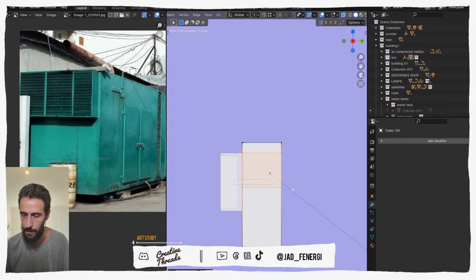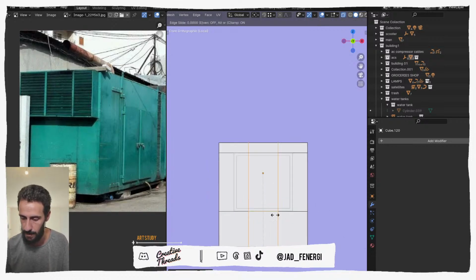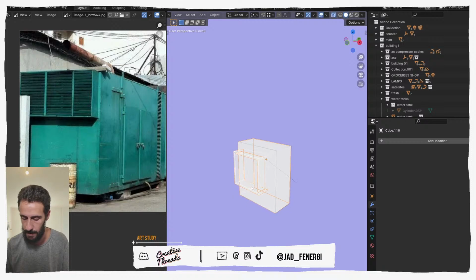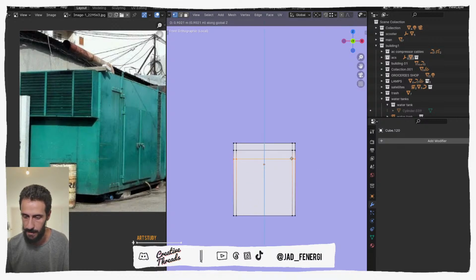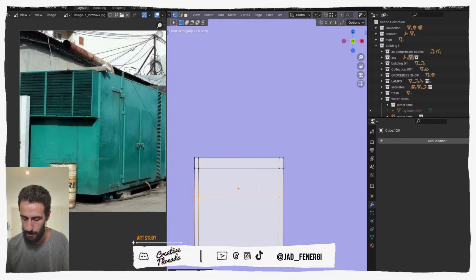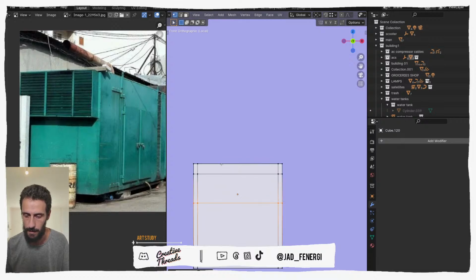When you do stuff with modifiers, you can usually turn them off and on. This is why procedural stuff is much better to deal with instead of going for this kind of stuff. So let's just delete this guy. That's Alt Z. And now what we need to do is just place things as they should be. This should go here. And all right. And the whole thing, if you press G on the Z, move it upwards, something like this.